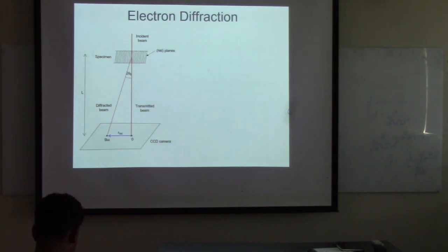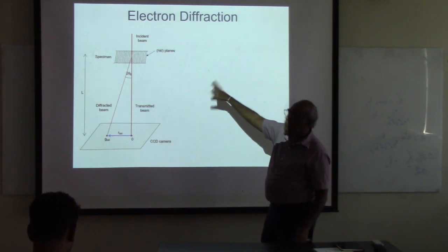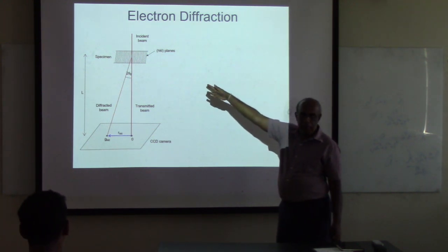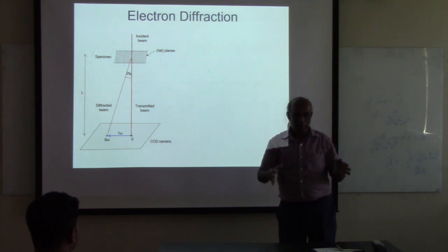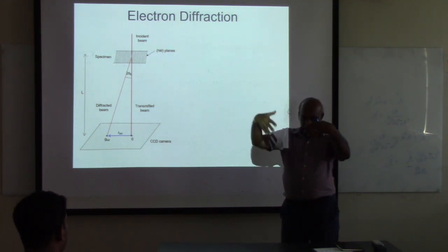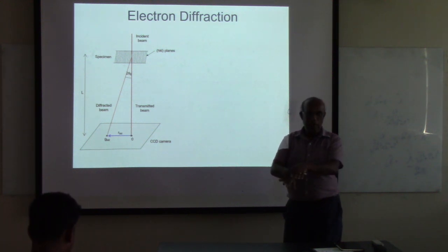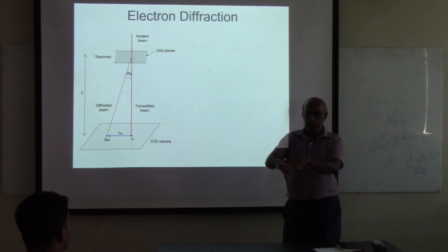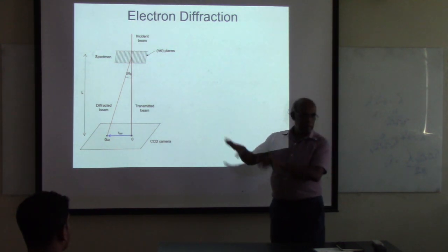Okay, so these are all about X-ray diffraction. You can do the same thing with electron diffraction. I don't know how many people have been to Luxor. We have the electron microscope. You can do electron imaging as well as diffraction. Typically we say SAED, that's selected area diffraction.